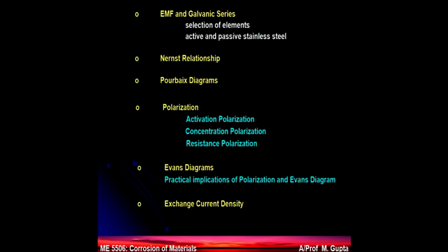If its weight is stable after 1 or 2 or 3 days, that means the oxide is protective; otherwise it is not protective. And if the combination falls in the immunity zone, then you are well placed. There will not be any corrosion. So those are the lessons we learned from the Pourbaix diagram.